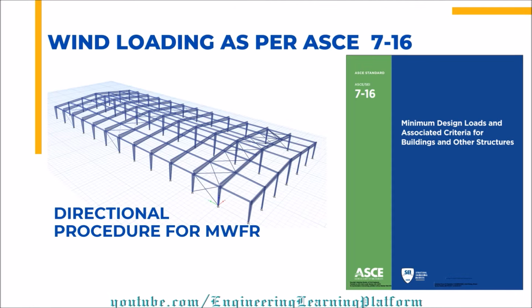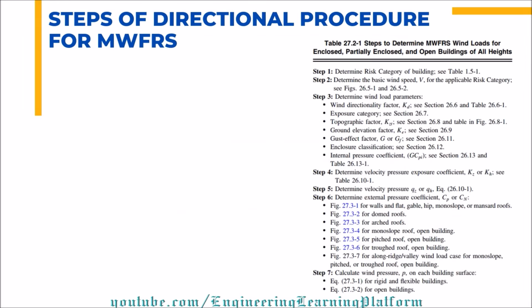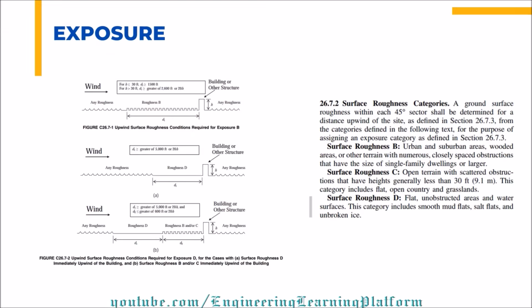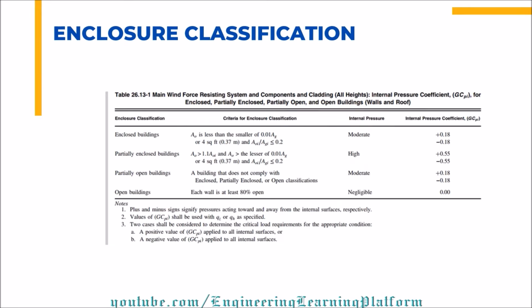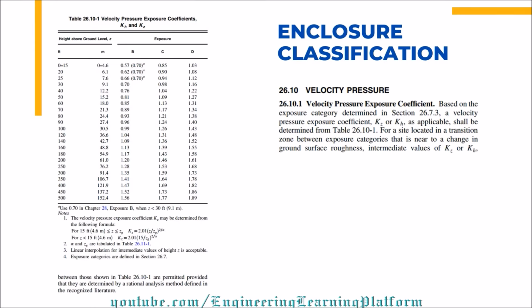Now as far as windward side is concerned, the pressure is applied in a trapezoidal manner, meaning at each height the pressure is varying. And that is due to this KZ factor. So KZ means for windward side, that at each height you calculate pressure.